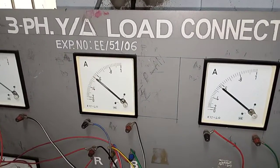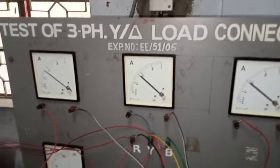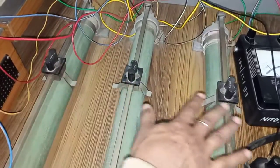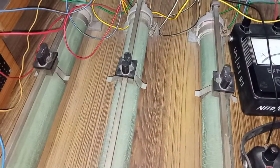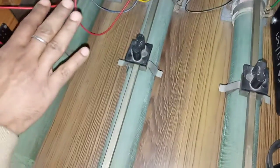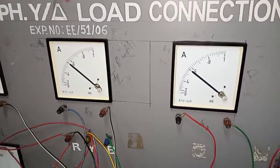This is also in the range of 0.56, but A1 is slightly less. It is in the range of 0.53. So you note down 0.53. There will be some difference because you can see here, the loads have no marking that this is the equal position. Each is not identical specification wise, but manufacturing wise there can be some differences. So to identify the exact same location for each of them is a bit difficult. But A3 is showing us the line current and A2 is also showing us the phase current. So it is almost equal, so we can say line current and phase currents are equal.